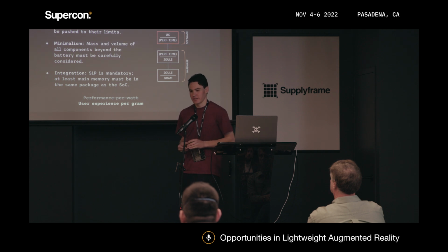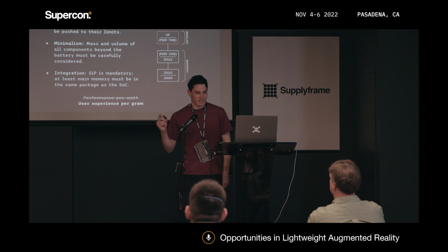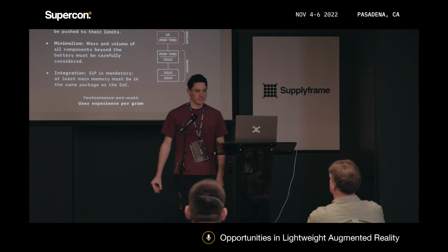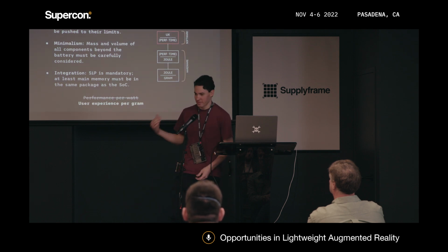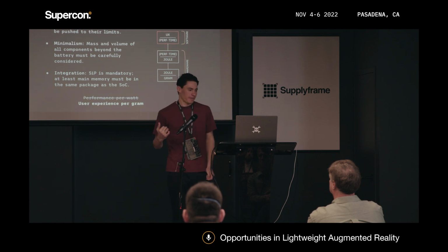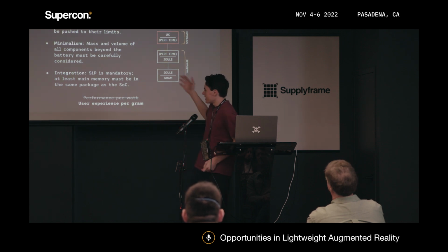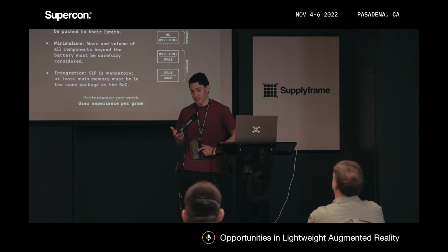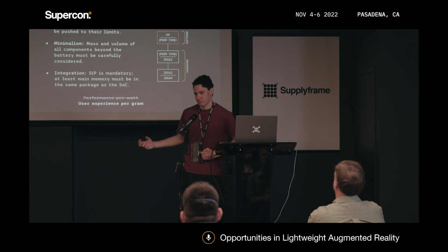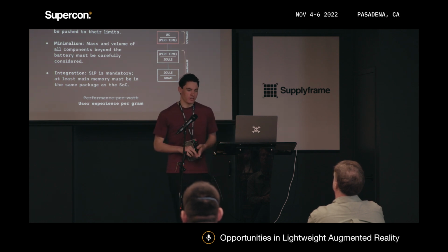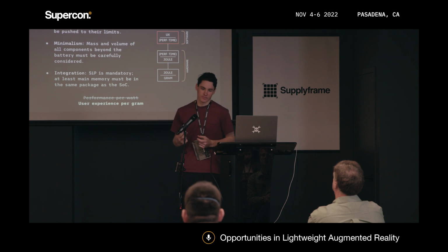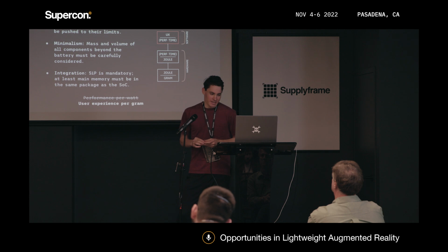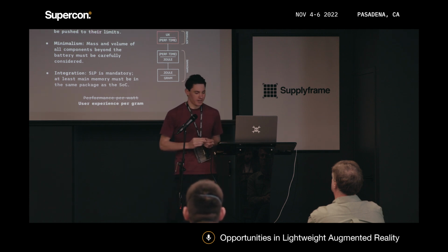So, you have to try to go into low power modes. The STM32MP1 does have a Cortex-M4 coprocessor, so there are some interesting things you can do with that. But in general, I needed to look for ways to take advantage of low power architectures, ways to eliminate extra components like external bridge chips that consume more power converting between display interfaces. And of course, as I learned from the start, integration of components is going to be very important.